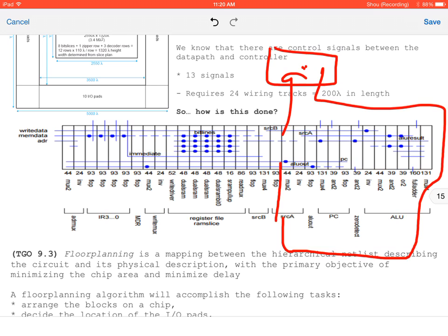So you have pads known as power pads. You're going to have VDD and ground. You're going to have power rings, which properly regulate how the power is distributed throughout your circuit, because you have to worry about clock tree synthesis. So part of this floor planning algorithm is you have to decide which I/O pads are going to be used for what purpose.